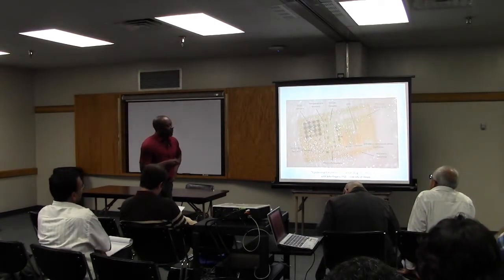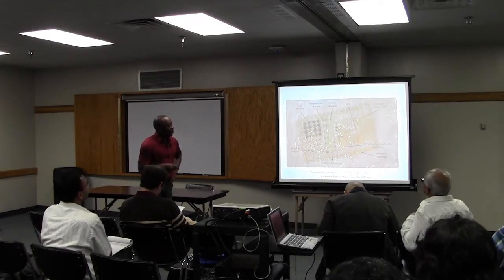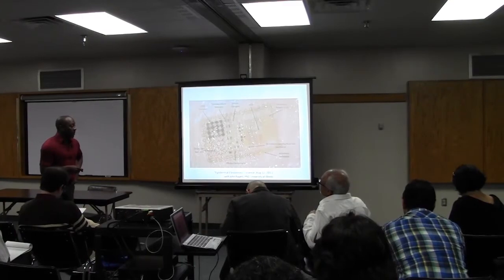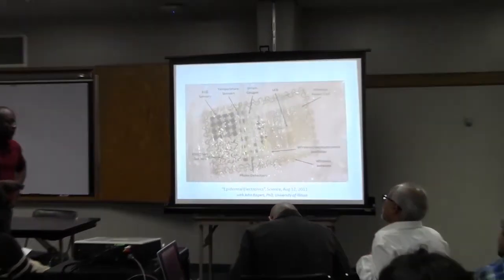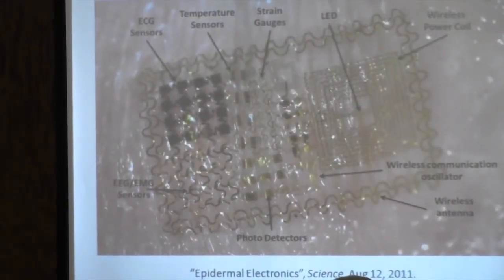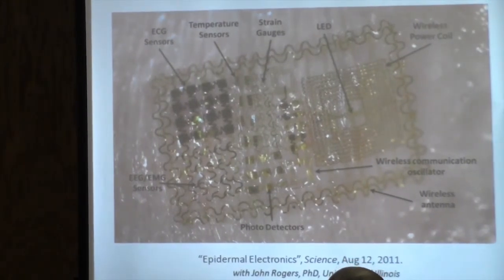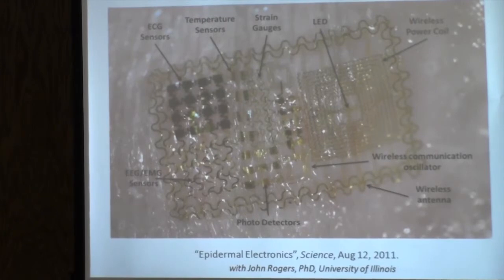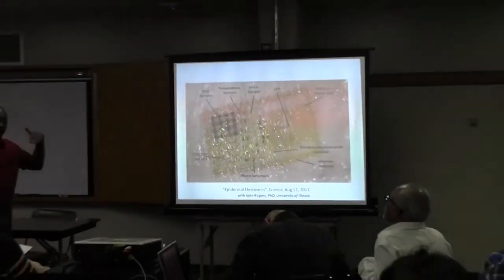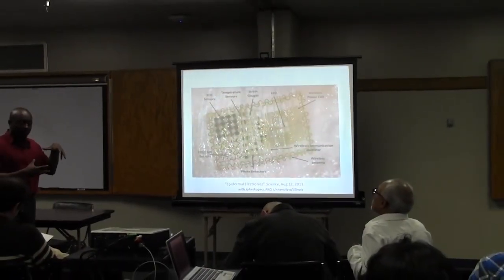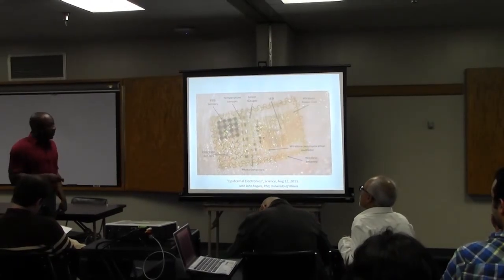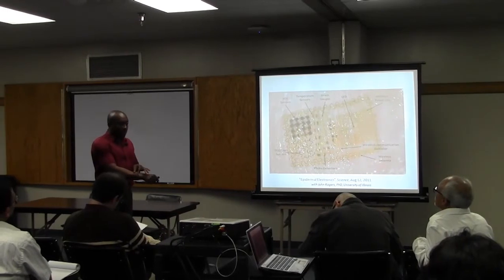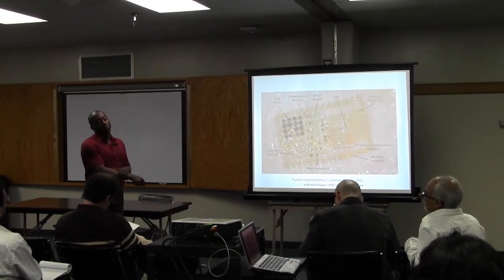There are interesting challenges here when you want to communicate on a system like this that can bend with your skin, right? So one of the things we're working on right now is we're trying to build RF antennas, right? So the resonant frequency of this thing is 2.4 gigahertz, irrespective of mechanical deformation. So this is fascinating from my perspective because in EE, we typically think that the antenna is on some flat surface, stuff is not bending. So all the engineering you do as an EMAG person, right, is somewhat trivial. But now we want to have another robustness criterion where even when your skin naturally bends, I want that resonant frequency to always be at, let's say, 2.4 gigahertz, right?